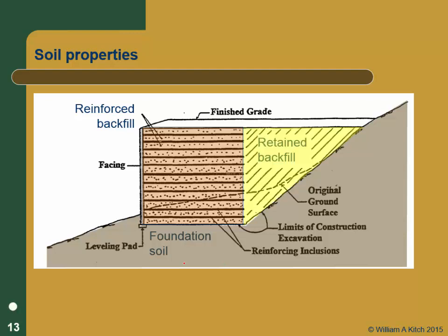The soil behind the wall is called retained backfill. That's often also select material. It could be the same material as what you use for reinforcing the soil, but it's a completely different function. This is the material that's actually going to generate the lateral earth pressures on your wall, whereas the reinforced material is the stuff you're actually going to try and calculate pullout capacities and anchorage length for your reinforcement and all that stuff. So the best way to think about it is, this is your wall.